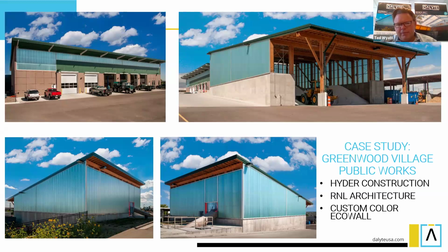Again, you can see for the most part, just a perimeter frame. In some areas we did a butt joint for expansion. But again, you have a single panel running from head to sill. About every 10 foot vertically, depending on the wind load, we do need a horizontal purlin. You can kind of see that on the top right. They have a pretty heavy-duty wood structure, actually more than we needed, but again, a great system.